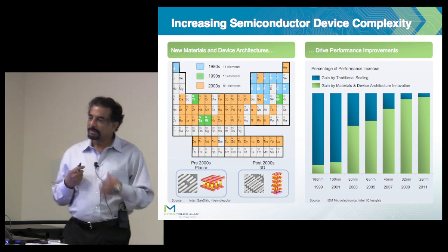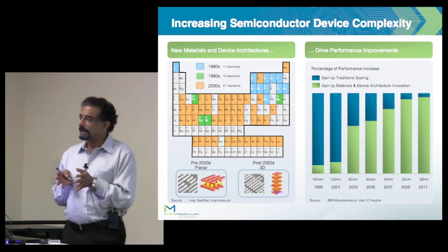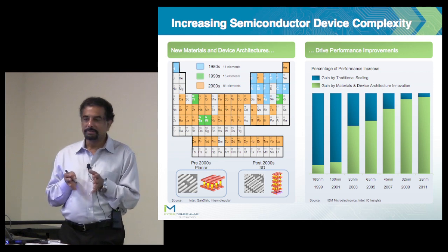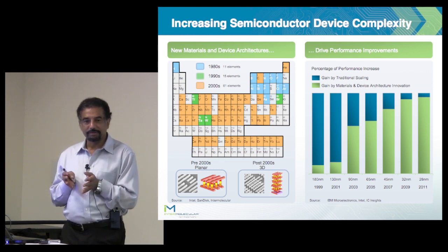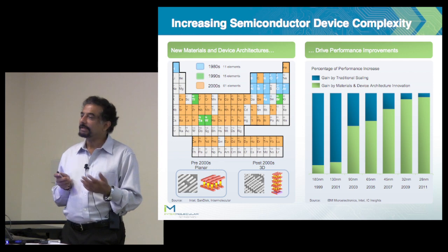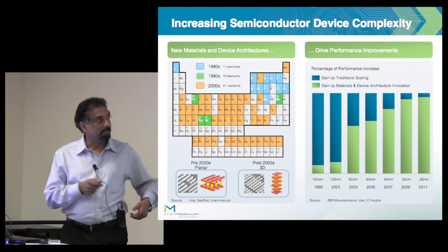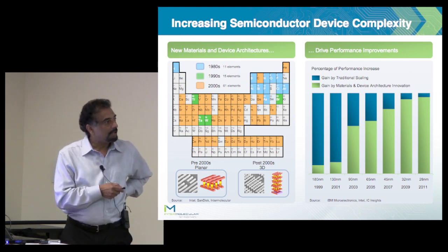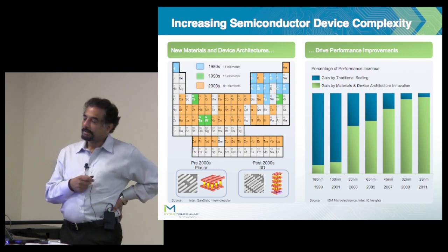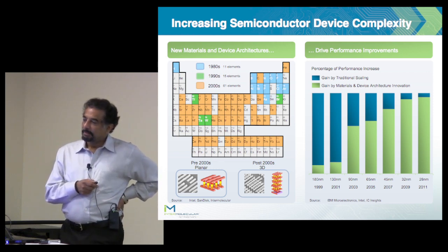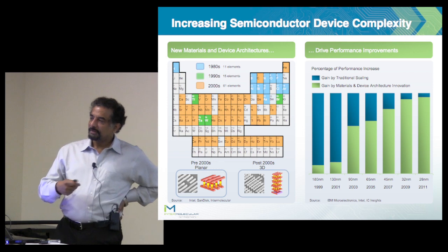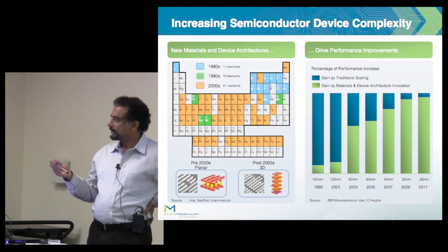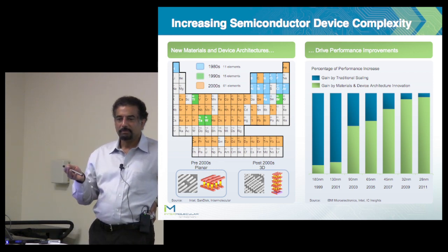And if you look at what has been driving this, it's not only about scaling, but about improving performance. We want more and more drive out of the transistors. You want the interconnects to handle larger and larger frequencies. Typically in the past, the performance automatically came as a result of the scaling. And I think some of you would have probably heard about the scaling introduced by Dennard,